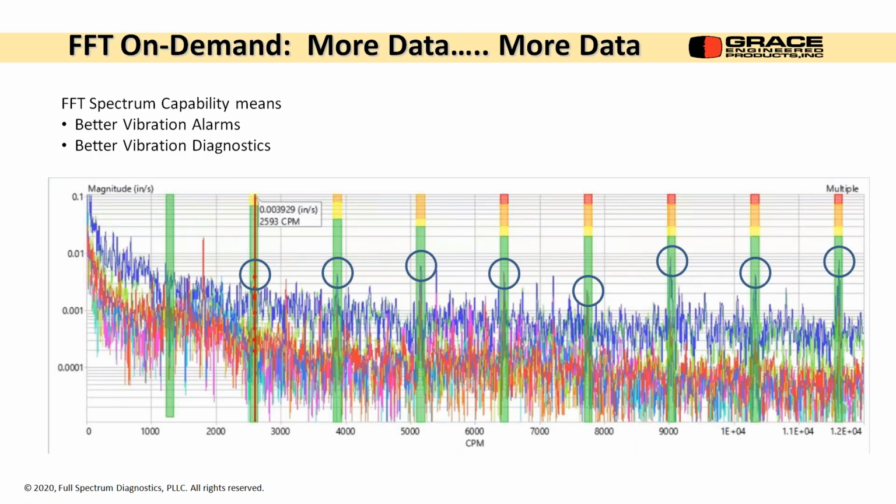This is another vendor where they narrow banded everything. This is a rolling element bearing raceway frequency, and it was on a gearbox, and it was just buried in the noise floor. So we have to put it on a log scale, put some specialty alarms in it, and we could start picking it out. So there is a lot of things you can do with the databases as far as pulling things out that are very subtle.